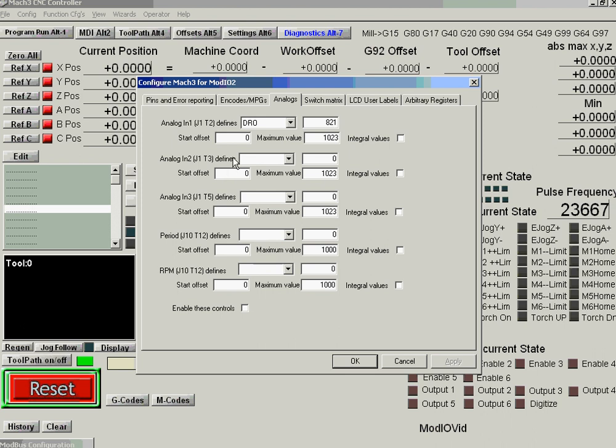It doesn't say how to turn a value which actually goes from 0 to 100% into the values in our DRO. Now for a feed rate override we probably want to go from value, it's a percentage, so we probably want to go from value something like 5, and we probably want the maximum feed rate override to be, well, let's say 150.